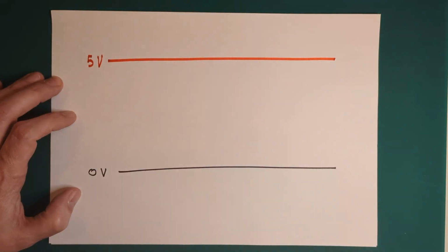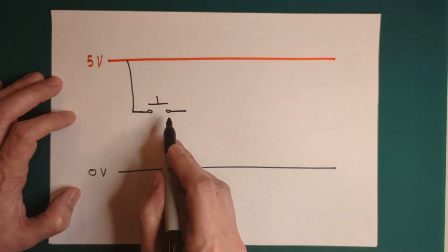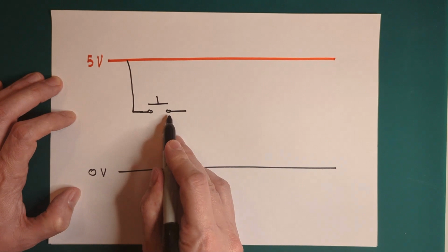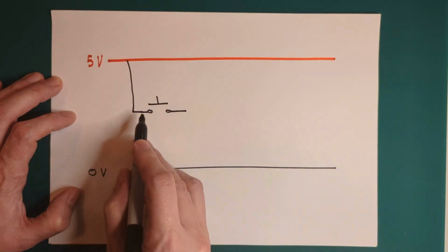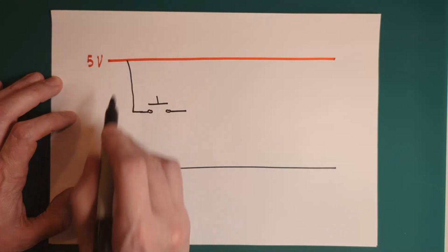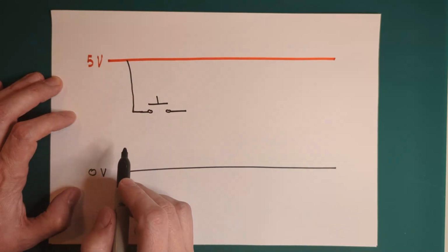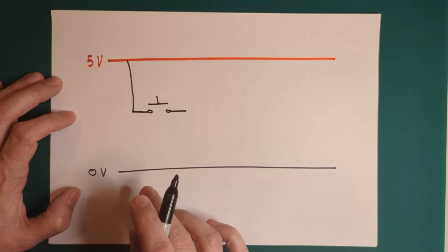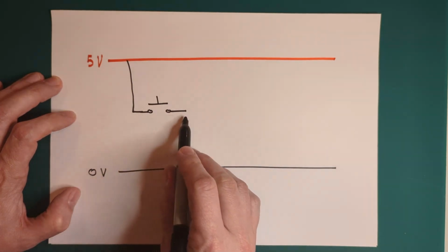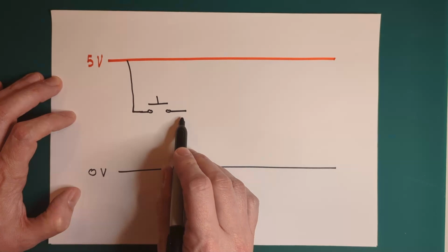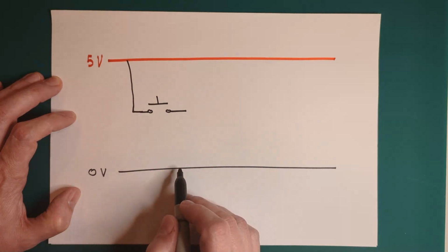There is a combination of factors here causing problems. Let's draw a diagram for this. In the push button, I want to select between 5 volts and 0 volts. And I have this wire going to 5 volts directly, so I get 5 volts when the button is pushed, and that seems to work. But when I release the button, I don't want this end to be disconnected, but close to 0 volts.